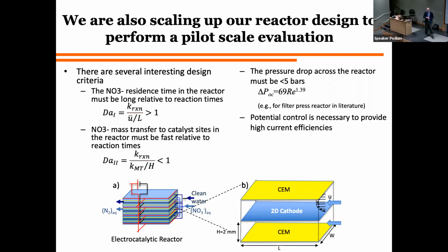Yeah. Advantages or disadvantages to operating small reactors in parallel with one large reactor? There must be. I don't know where the right trade-off is. This is certainly too small. When I look at the chlor-alkali industry, they use plate reactors quite a bit. Those are maybe on this dimension, right? And they'll be in parallel, right? So based on industry experience, the scale is probably somewhere from here to here, and then it has to be in parallel. You can't get enough flow through one cathodic and one anodic chamber for this.